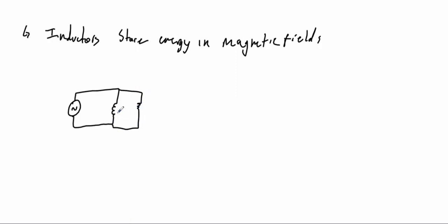If I were to build this, let's think about what happens for very low frequency. At low frequency, the electricity could go through the resistor or through the inductor. And at low frequency, there's not very much back EMF because the change in flux is small, which means this thing is basically a short circuit. So low frequency passes.